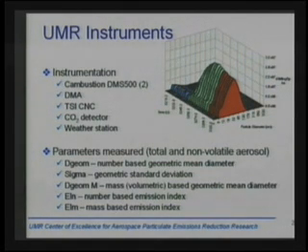We use a device based on the principle of differential mobility analysis that allows us to measure size distributions as a function of time. So this is some typical data from a real-time differential mobility analyzer that allows us to get a size distribution at a frequency of 10 hertz, 10 times per second. We're plotting in time here, the particle diameter here and the differential concentration here. And in fact, just as an example here, we go through a transition from idle to maximum power, just to show you that things are dynamically changing in terms of the size distribution when you do that. So we've got a capability to get inside the time frame of those sort of processes, although actually in this study we didn't pursue the transients.